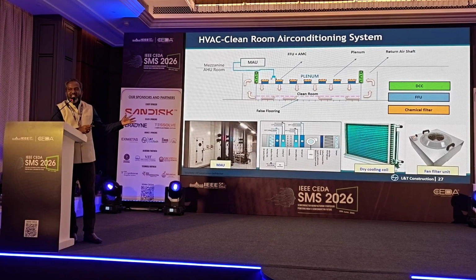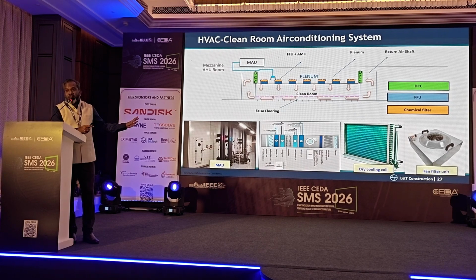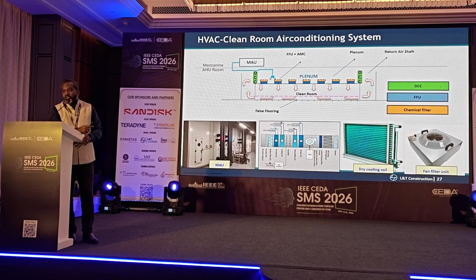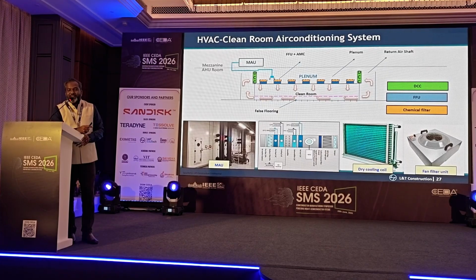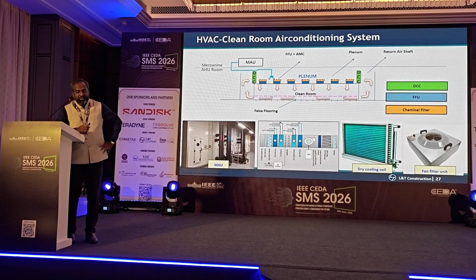We have scrubbers next to the fab itself. Our own scrubbers could contaminate our makeup air unit, so we should have a lot of chemical filters. A lot of study goes into what kind of filtration is required in makeup air units based on the locality, right? So that's about the HVAC.